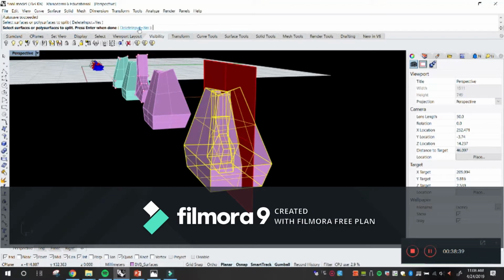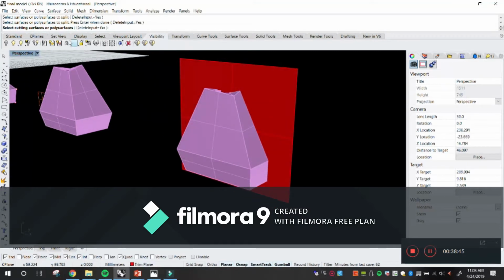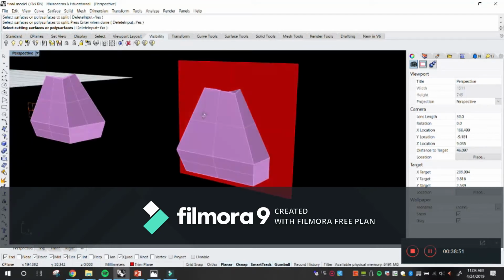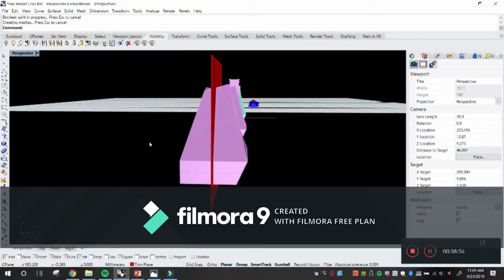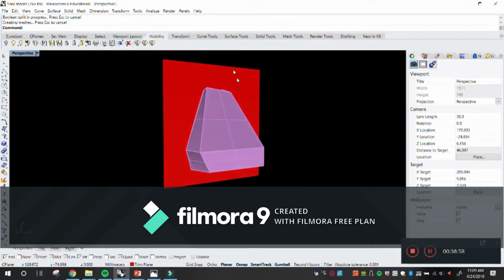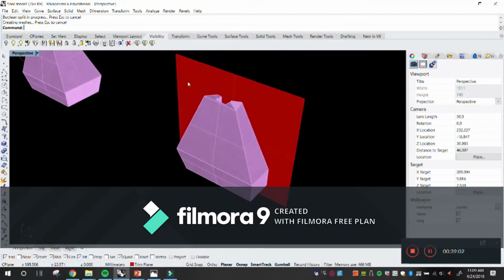Now notice it's asking you right here, do you want to delete input. Right now I set it to yes. Let's see what happens. So enter. Select cutting surface or polysurfaces. Delete input is equal to yes. So what's the cutting surface? The red. So we select that. Press enter when done. And then that happens. Not sure why it's not deleting the input. It's actually something that's helpful.